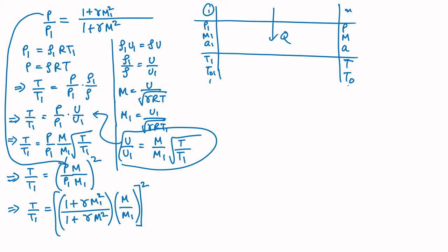Okay, now to develop the relationship for stagnation temperatures, of course stagnation temperature is essentially a measure of the total energy of the flow, both the static temperature plus the kinetic energy. Which is better quantified by the stagnation enthalpy H0, equal to H plus U square by 2. So, this is the stagnation enthalpy or total enthalpy.